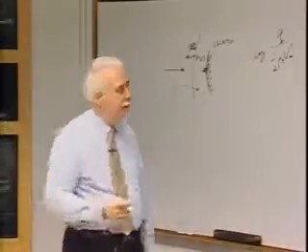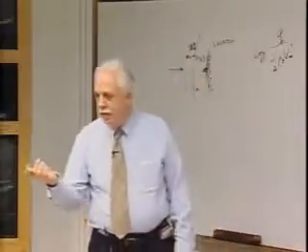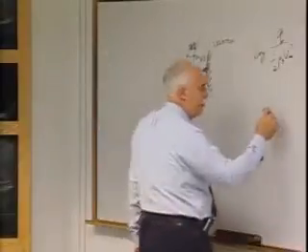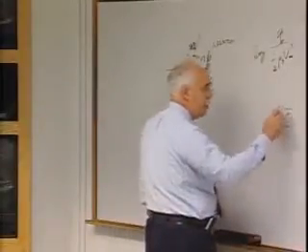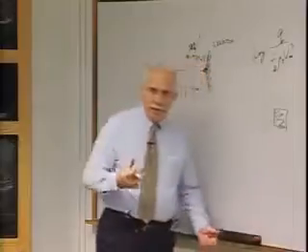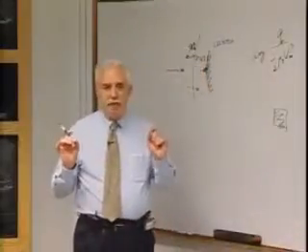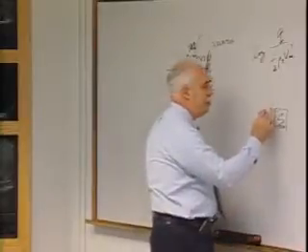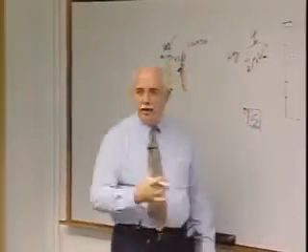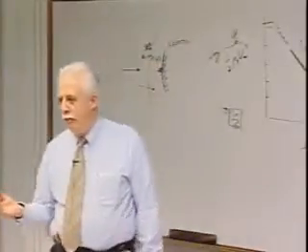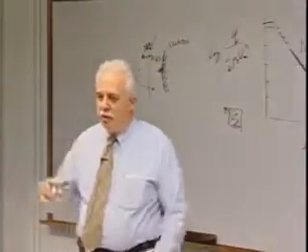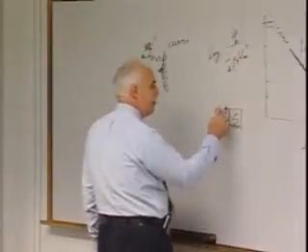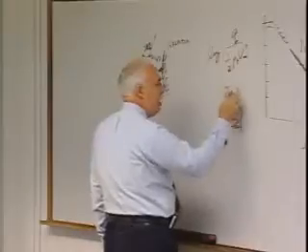Now in the ablator, that char, think of it as a charcoal briquette. You start with some material, it degrades and all sorts of chemical reactions go. If you've got a good ablator for our application, what happens is you're left with a residual char, which is black and very high emissivity. It's pure carbon if you want. That's the challenge, to get a carbon surface or a high emissivity, high temperature surface that can re-radiate.